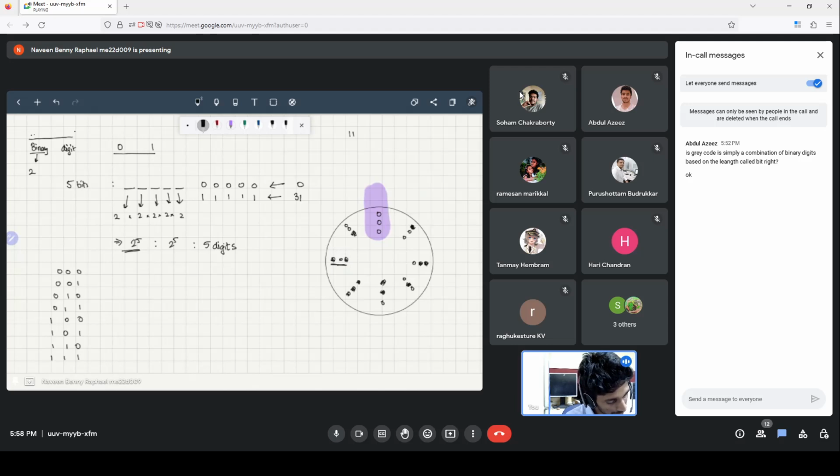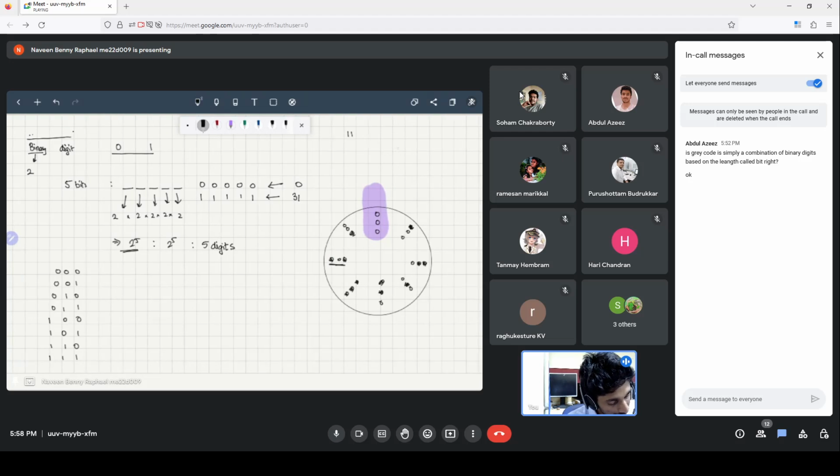When filled-open-filled comes here, only one of the lights will go through because the other things are blocked. So if you have a sensor on the other end, that sensor will read no light, one light, no light, which in this case will represent 7.